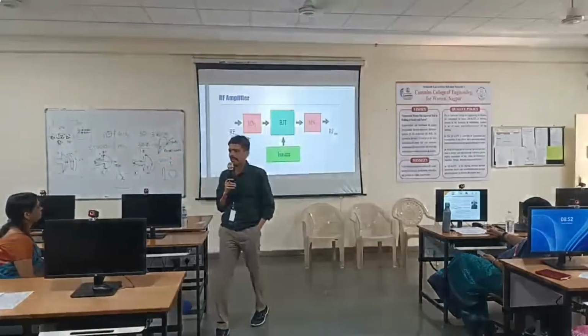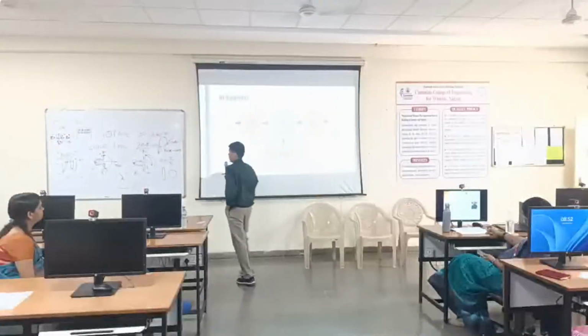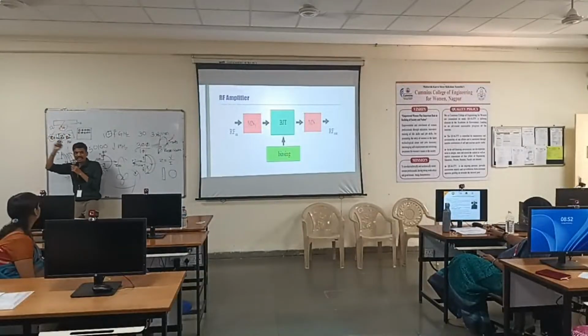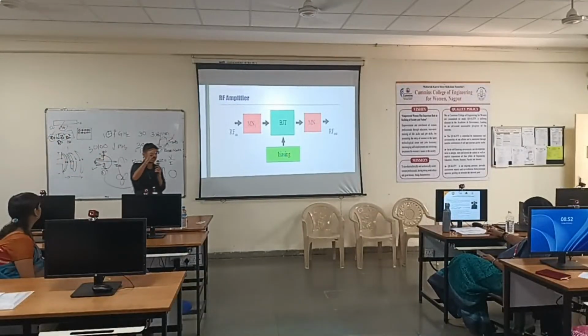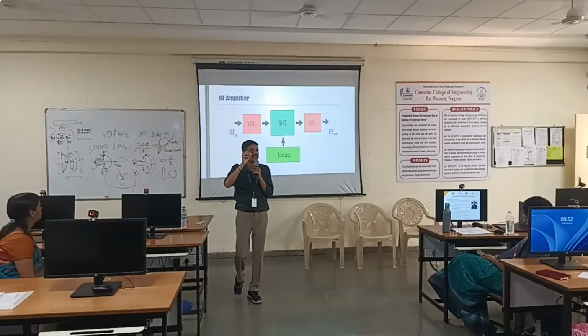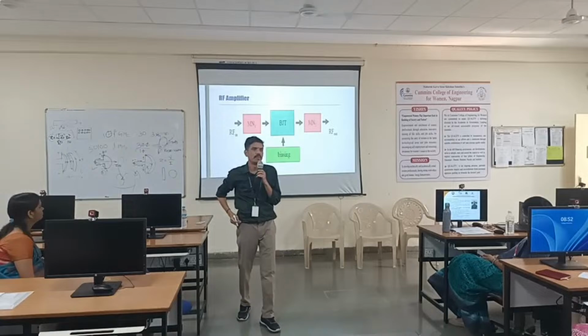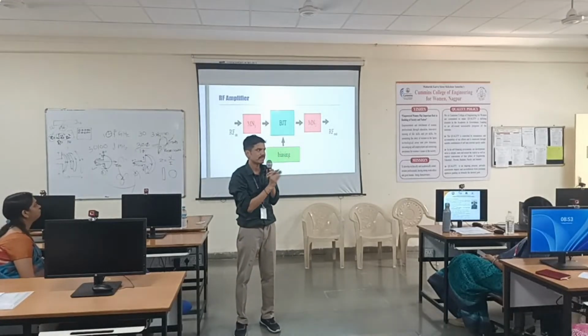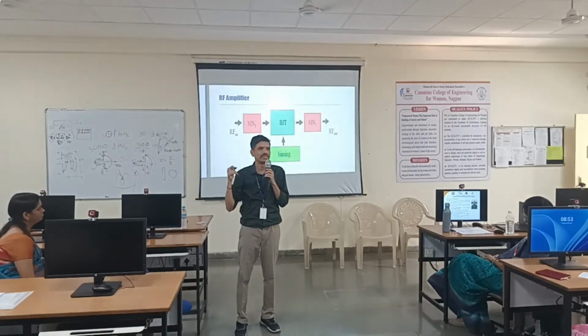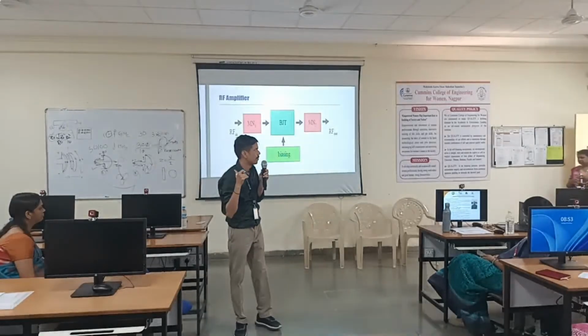The major problem is it will work best for one single wavelength. That means if you design at, let us say, 3.5 gigahertz, this will match 50 with 10 best at 3.5 gigahertz only. The moment you change the frequency, lambda will change, its length will vary, lambda by 4 will vary. So this is a narrow band matching network.